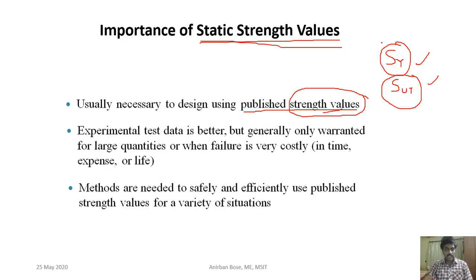And remember, these are static strength values. That means the load that is applied is a gradually applied load; those are basically for static design, we use this data. Now, experimental test data is better, but generally only warranted for large quantities or when failure is very costly.